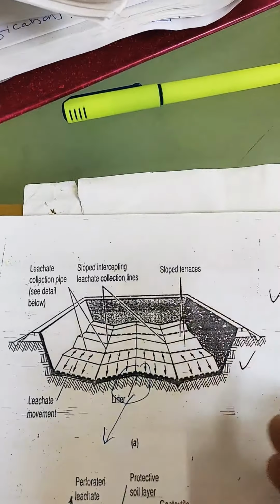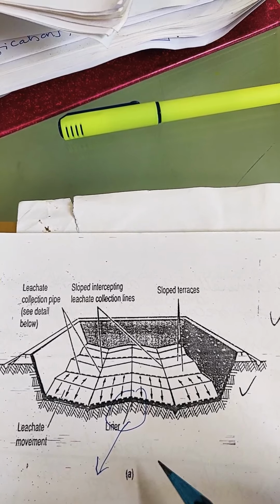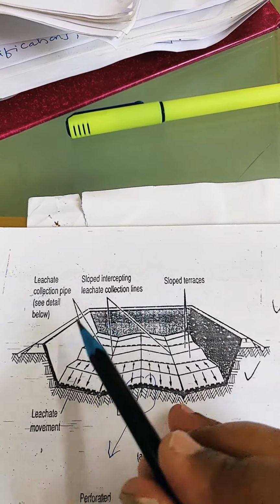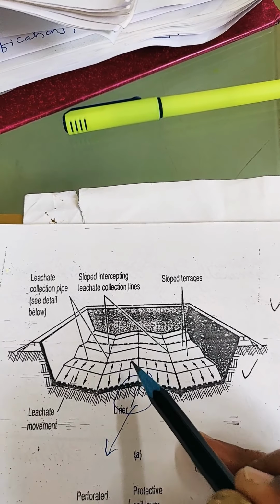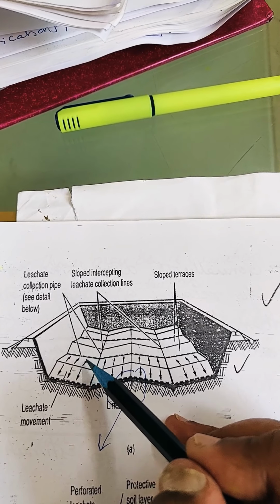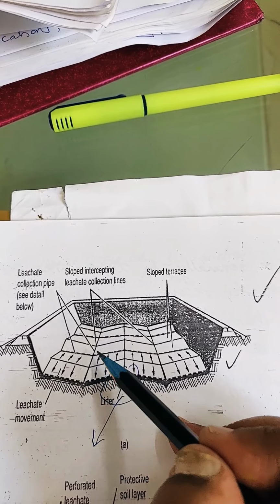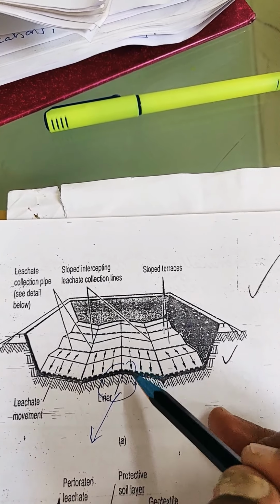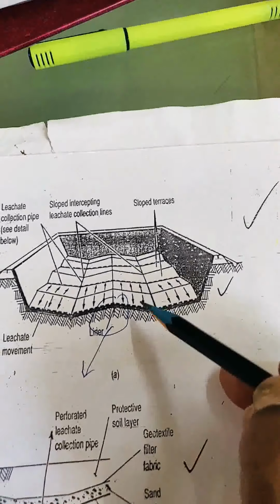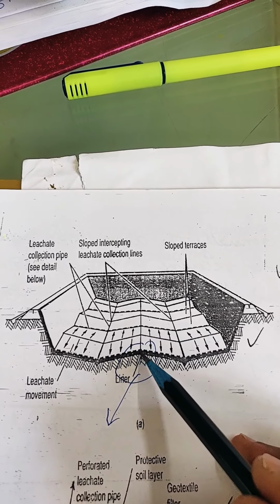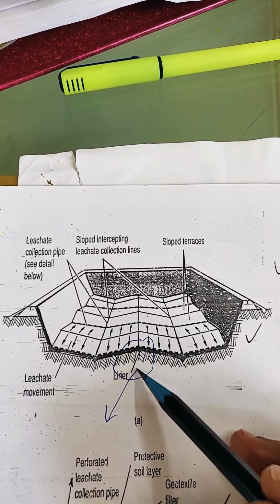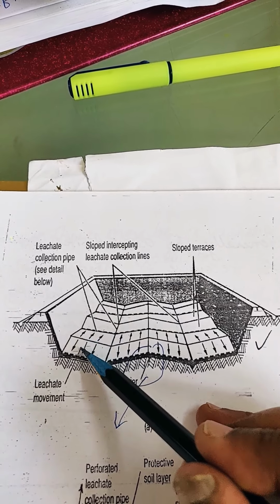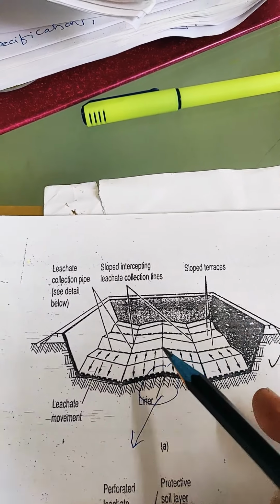Now I am going to show you a typical landfill site and how the layout is done. See this solid fill. Bottom slopes are made so that whatever liquid goes through this sand liner enters the pipes here, which are run like this. Through this micro pipe system it will be removed. Here at the bottom there will be clay liners. It is written here. Liners will be there, and these pipes. Liners will not allow the leachate to percolate to the ground. So the leachate movement will be towards the pipe. It is made a little higher, and here you will have all the solid waste filling.